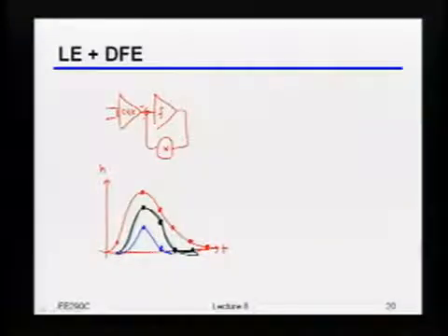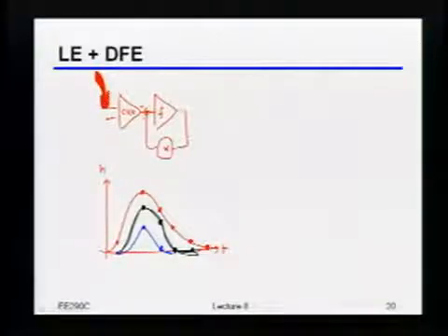Turns out a lot of times people will do these DFEs not because it's actually thermal noise that's being amplified that causes a problem, but just because there's a lot of crosstalk that you might be picking up at the input of the CTLE. And so if you try and do everything with a linear equalizer, you'll amplify that crosstalk. Okay? So even just from that standpoint, oftentimes you'd want to do the DFE just so that your continuous time linear equalizer won't be peaking the crosstalk, right? Which really has nothing to do with thermal noise, but for the same reason that it peaks thermal noise, it also would peak crosstalk. Okay? Does that kind of make sense to people, or?